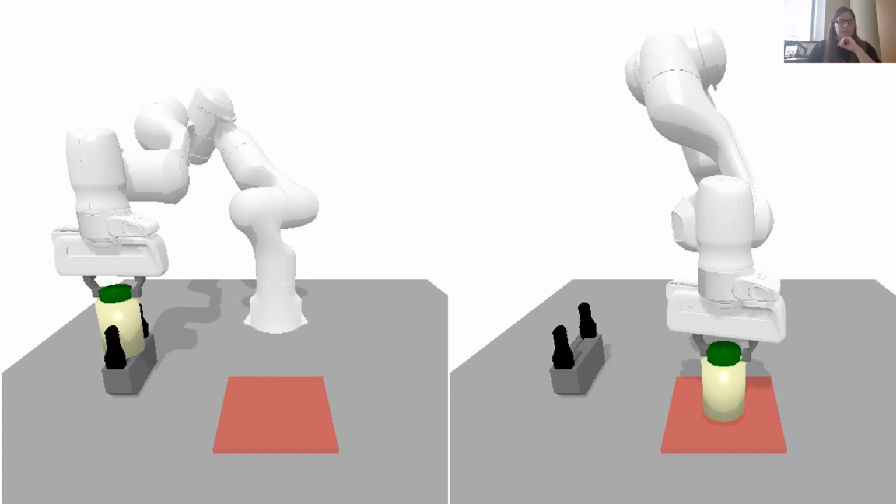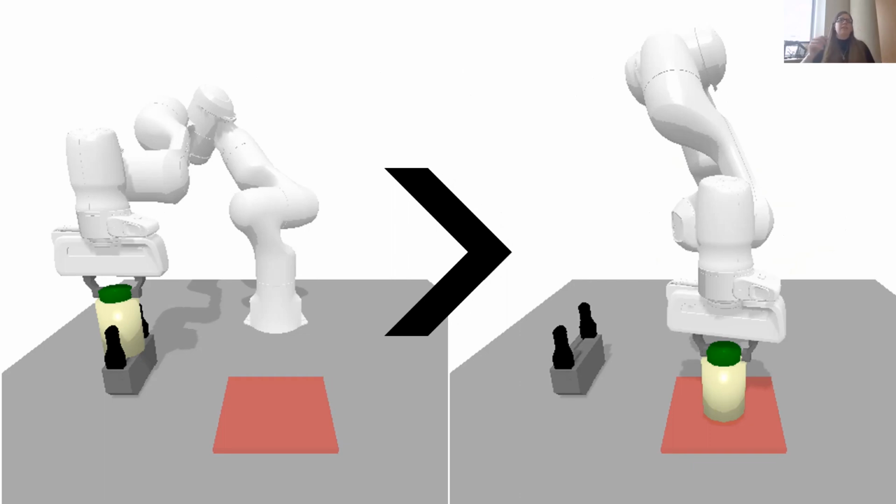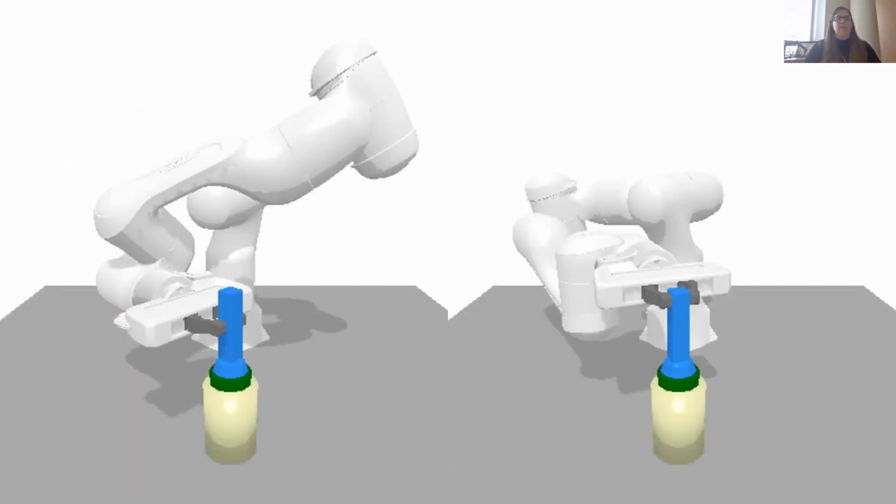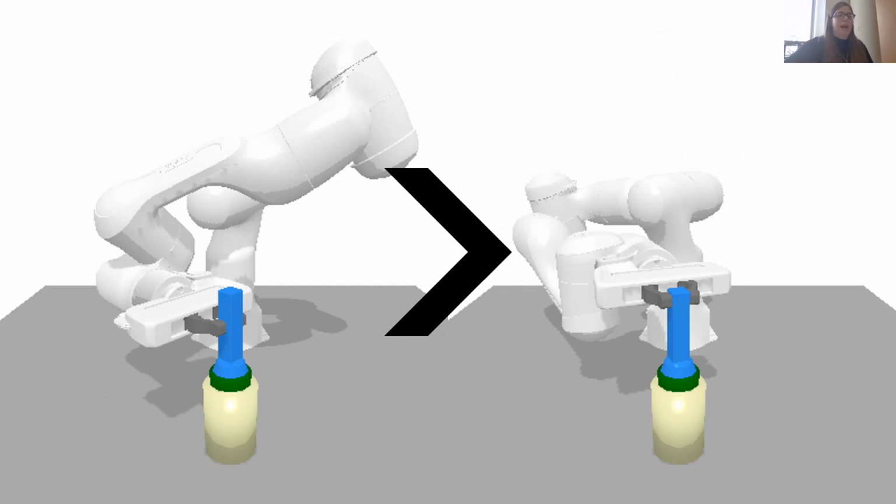So in this case, given the choice of do I fixture using a vice or do I fixture using frictional contact, the robot can reason based off that cost that it is more robust to use the vice, effectively because the largest forces that you are experiencing are now being maintained due to kinematic limits, which are more robust than using frictional limits. In addition to these more global choices, the robot can make smaller choices, such as given the choice between two grasps. By checking for that robustness and evaluating that cost, the robot can choose which is the more stable grasp. So this is a very first step towards how we get our robot to make more robust choices.